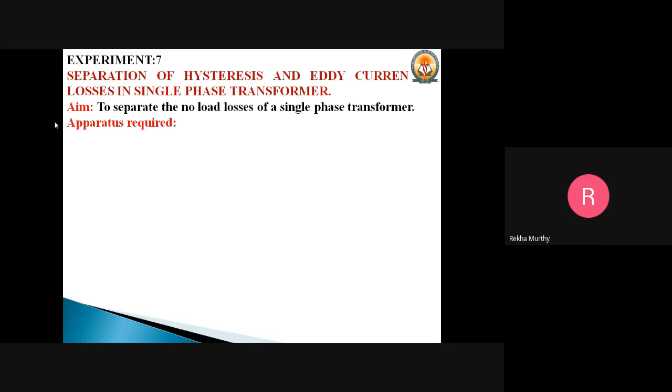Therefore, the DC motor should be connected to the DC supply. How to start this motor? We require one starter, that is a 3-point starter. In the 3-point starter, we have 3 terminals: L, F, A. L is line, F is the field connection, and A is the armature. L we connect directly to the supply, that is 220 volts DC.